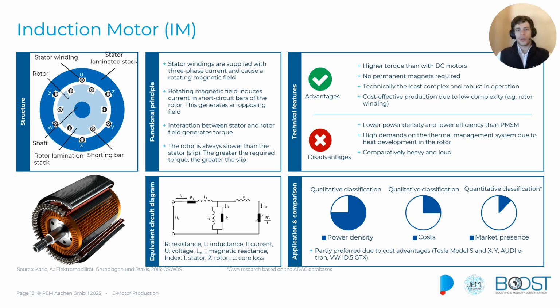Because of the minimal time delay of the induction, the rotor is always slower than the stator. This delay is called slip and explains why we talk about synchronous machines in the two designs before. This is an asynchronous design. In the PMSM and the EESM, the magnetic field of the stator and the rotor works synchronously without any delay.